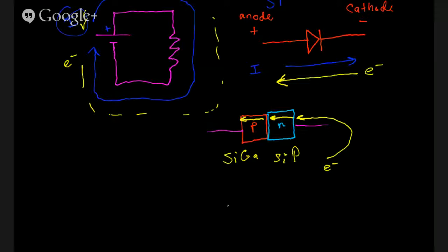And if we were to reverse that, let's say we have a higher voltage, higher potential on this side than this side, and we end up with our electrons flowing backwards, it would conduct through the n-type silicon, but there's no more holes for the electrons to go into once it hits the p-type and n-type junction.